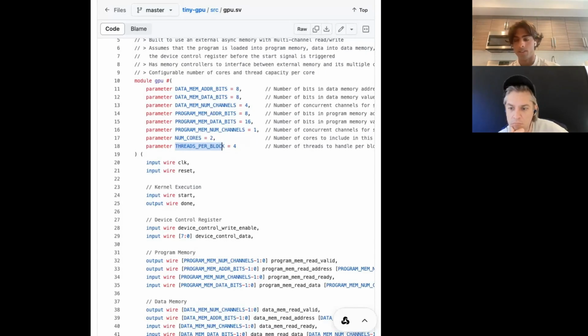The bigger thing is the bandwidth issue. So if I have 1,000 compute cores requesting some values from memory, and memory can only support 100 reads at once, that means that this is going to start to get queued up. So 1,000 compute cores request data, then 100 of them are going to get data back, then the next 100. Which means that certain cores, even if they're being processed together, might make requests to memory at the same time, but they may not get the data back at the same time because memory has an unknown latency. It's asynchronous. And that means that if one thread gets memory back earlier or later than the other ones, it may have to wait for the other ones, or there's a bunch of stuff that happens around that. So in my design, it waits for the other ones, which means it can't just keep going.